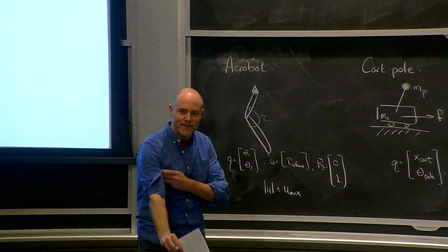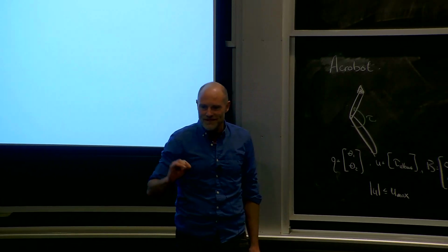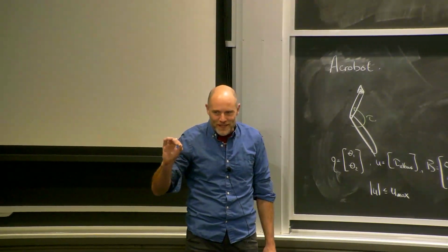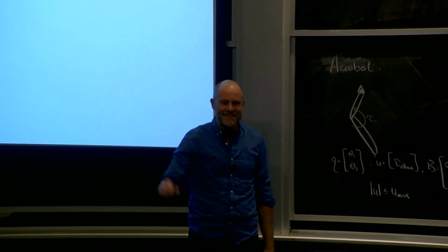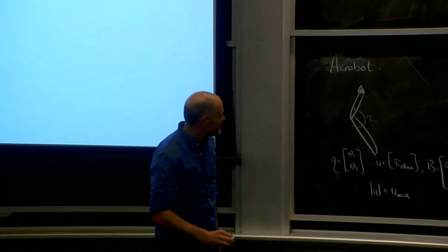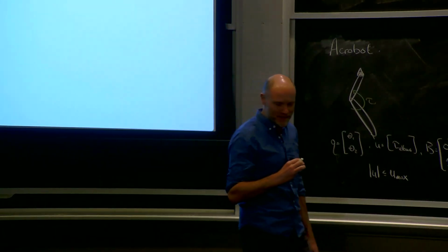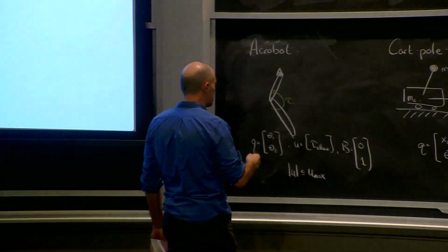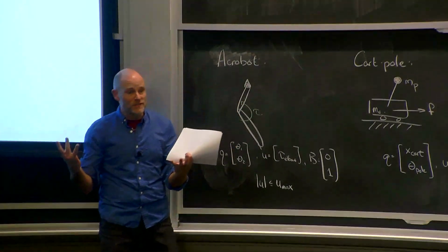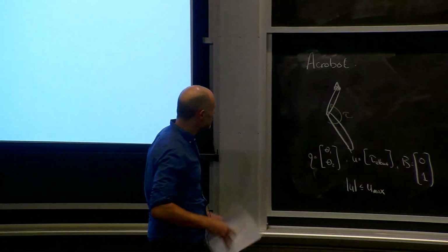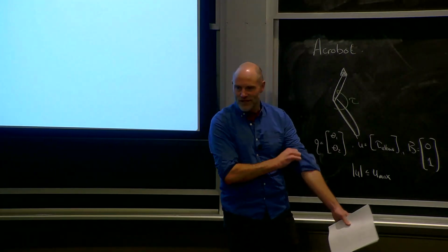It's kind of funny, right? If you look at the code for the OpenAI Gym Acrobot example, they have almost the right equations, and then there's actually a comment saying like, this doesn't look right, I don't really know what's going on here. So anyways, there's a right answer. There's two right answers, because that's why people get confused, because you can write the moment of inertia relative to the joint or relative to the center of mass, and that makes the equations look a little differently. So people are like, I see two different types of equations in the textbooks. One of them must be wrong. It's the same thing. It's just a matter of how you parameterized your inertia.